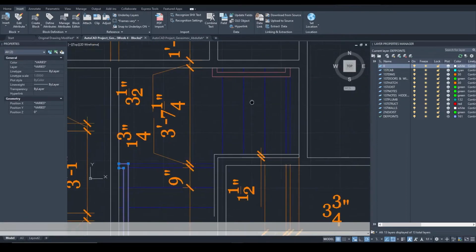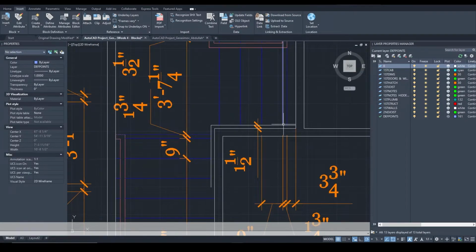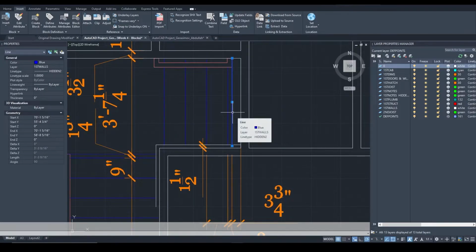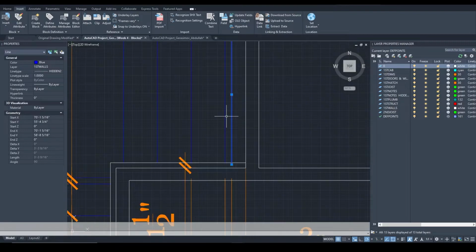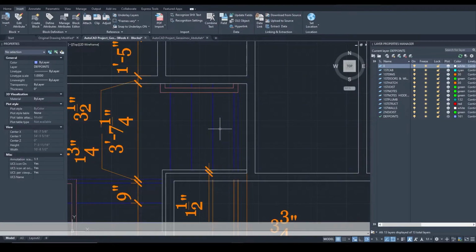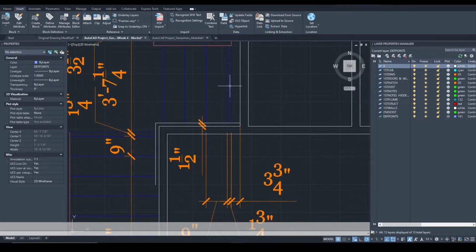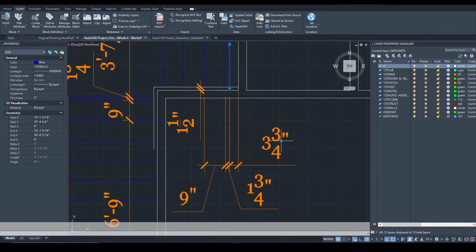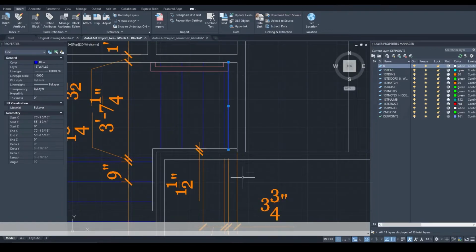Align this with, well, when we get to this point, this portion of the stairs that are going down into the basement, again, this line is going to be hidden too. The one adjacent to it on the left side is going to be a regular line with a bilayer line type, and it will be a 9-inch tread, and a 9-inch tread. 1, 2, 3, 3 of them. And offset the first line that is going to be hidden to 3 3/4 inch from this interior wall.